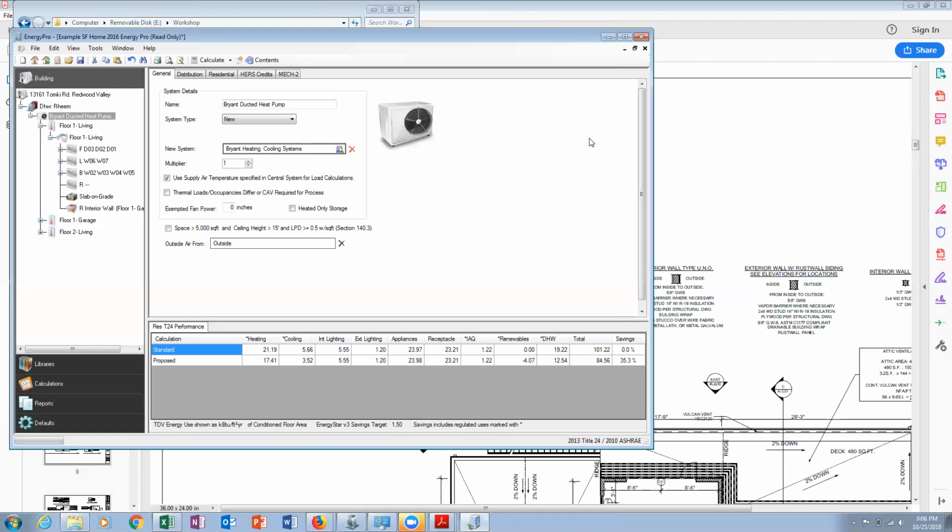And you guys could totally download the Energy Pro 2016 software, Energy Pro version 7, and you don't have to have a license to use it, but you have to have a license to execute a calculation. So you could build a model yourself and save it, and then you could send it to me, for example, and I can hit the calculate button. You could build your own model though. It's just you don't have the functionality of seeing if it actually runs, which is one of the hardest things in building a model: it actually calculating, making sure you didn't make any errors.